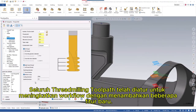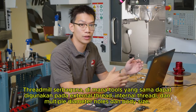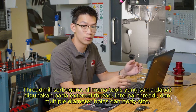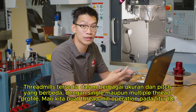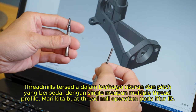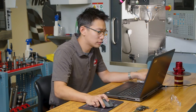adding some new features. Thread mills are versatile in which the same tool can be used on both external threads, internal threads, and multiple diameter holes and body sizes. Thread mills come in a variety of different sizes and pitches with a single or multiple thread profile. Let's create a thread mill operation on an ID feature.